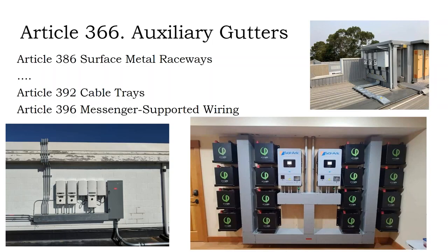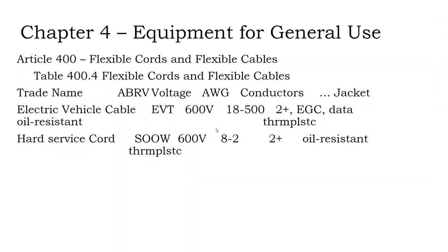If you're using a wet rated cable inside, like THWN2, but it's not rated to go outside a conduit, you would still need to respect the environmental ratings of the conduit. Just because you're using rain tight fittings on EMT conduit doesn't mean the inside of that conduit is in a dry environment.